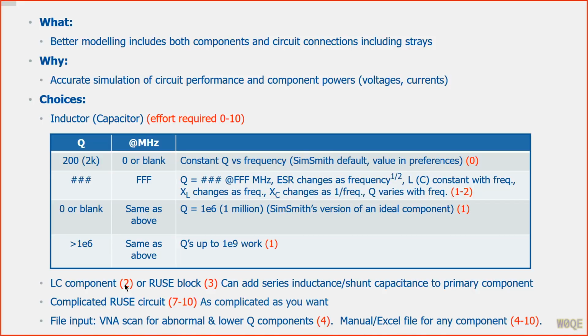This is valuable to do if we want to build some kind of a wide band filter. When I say wide band, I don't mean wide passband filter, but a low-pass filter where, say, you wanted to build a 10 meter low-pass filter and you wanted to stop the harmonics. You've got a harmonic at 2 times 10 meters and 3 times and 4 times and 5 times. Pretty soon you're up there to where you're very close to the resonant frequency of the inductors you use. And it's very important to include the effects of that in the design of that filter.